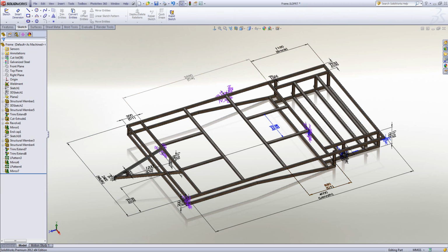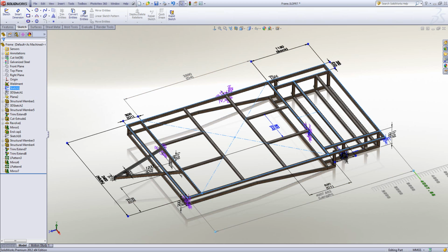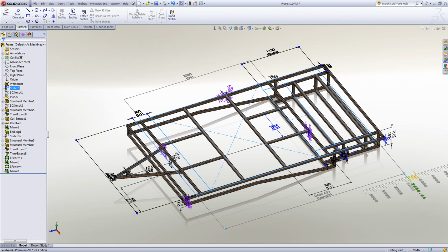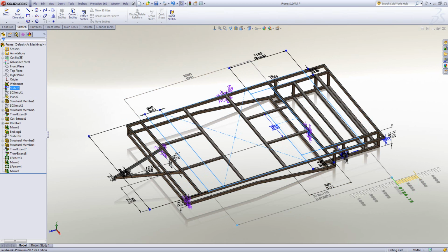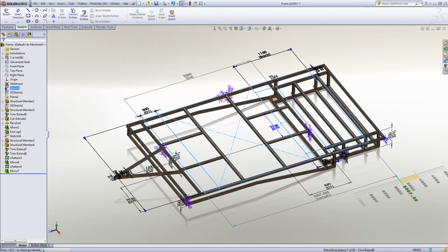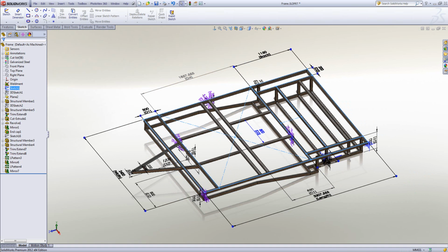And we'll have the other equations created on some of the other dimensions as well. So the first one I'm going to create is based upon the back of the design. You'll see if I click on my sketch 1, I can drag the size of the thing around. I've got instant 3D turned on, which means I can drag it dynamically. But you'll see as I drag the item at the moment, none of the design is really updating. It didn't have those kind of sketch relations we've just talked about.